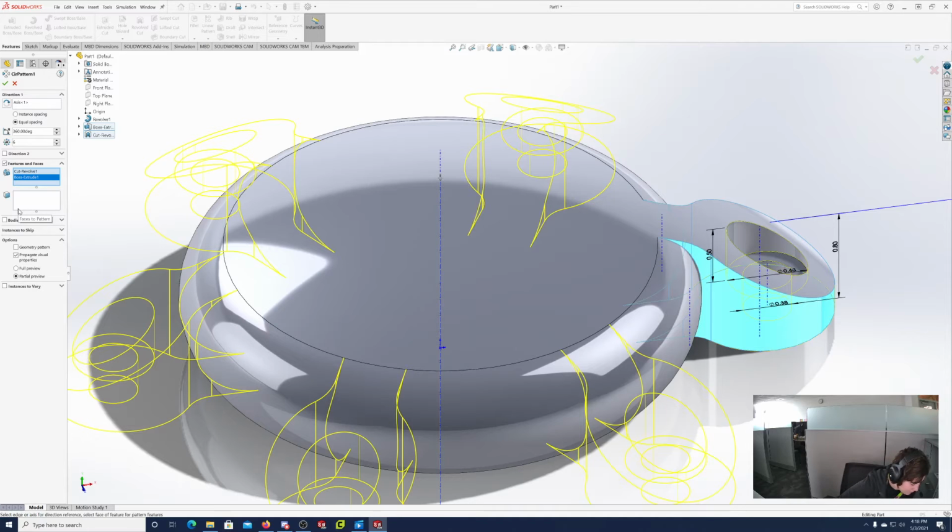And let's see. The pattern angle should be 360, which just means that it goes all the way around. And the spacing, let's see, does it tell us? We want equal spacing. The book actually, because we have a newer version of SolidWorks, every once in a while you'll see something where it doesn't look quite the same. So in the book, there's just a checkbox with equal spacing, and you want that checked.